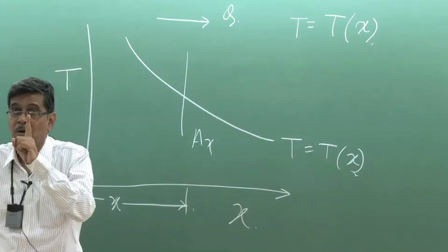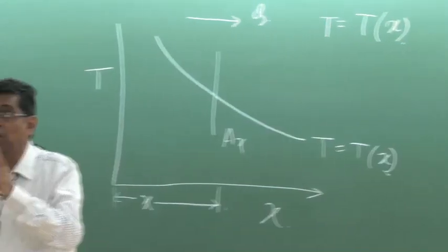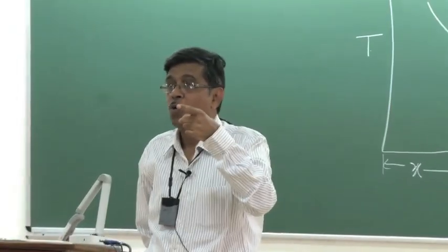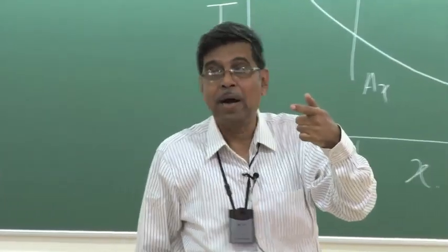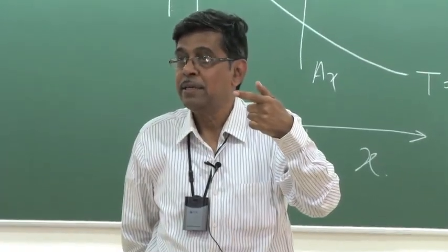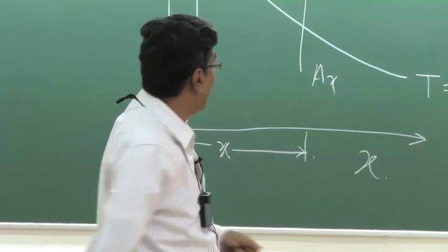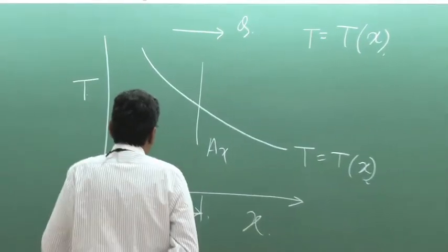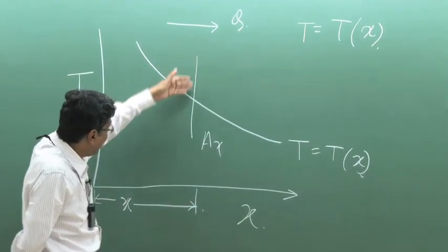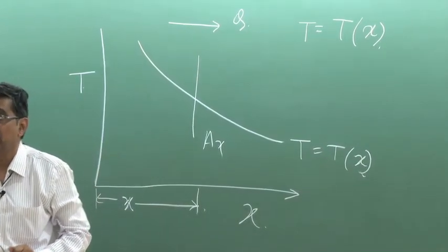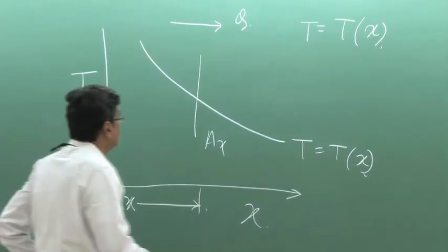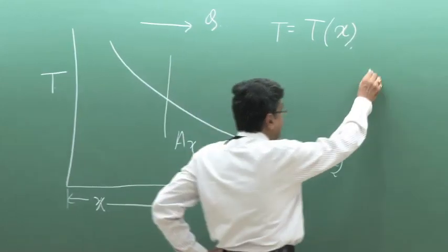Now here one thing is very important: when we define the heat, we define its direction. Heat is flowing in one direction. Okay. Now why have I taken an area normal to the direction? This is because in this connection we define a quantity, heat flux.